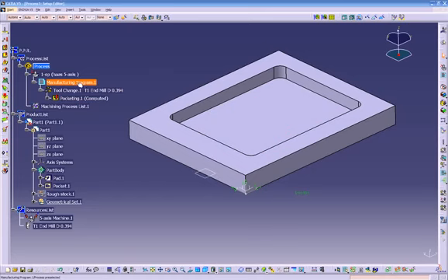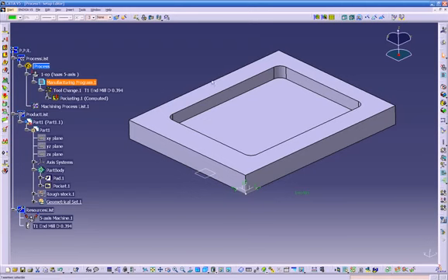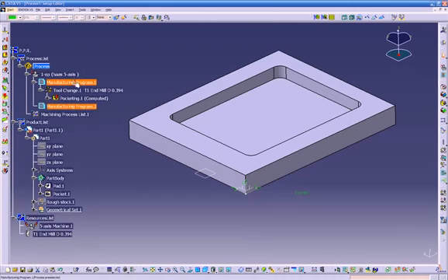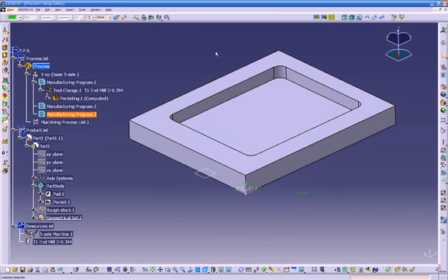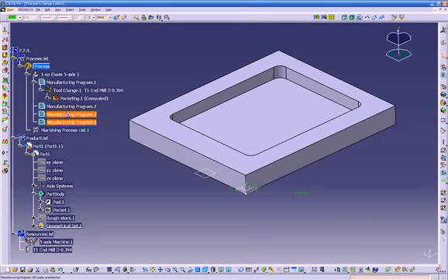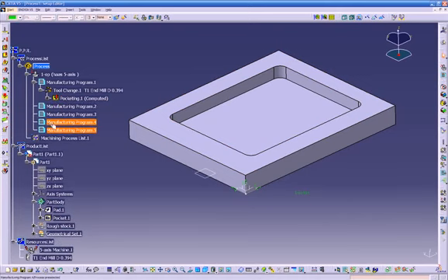But what I want to do, for example, you want to create different manufacturing programs in here, right? So once you click on this, for example, you want to create more manufacturings. We got the same thing on the bottom right here. It says select a reference operation to insert a new one after it. So once we click on this, we get a new manufacturing program. So you can create as many as you want to keep this organized. If you want to have just pocketings over here, or only drilling over here, it's up to you.